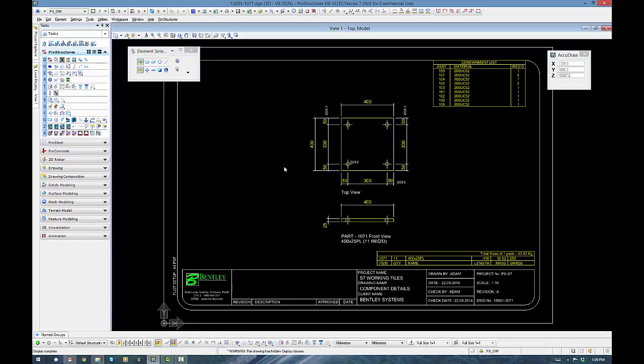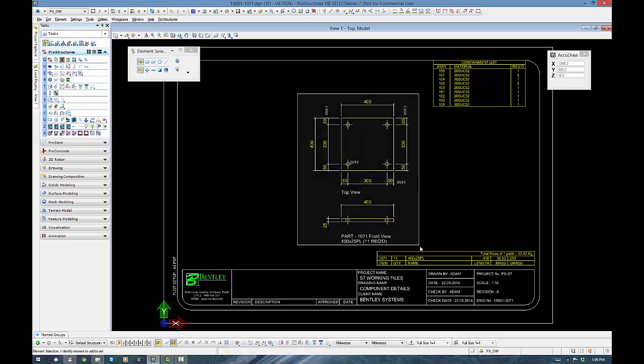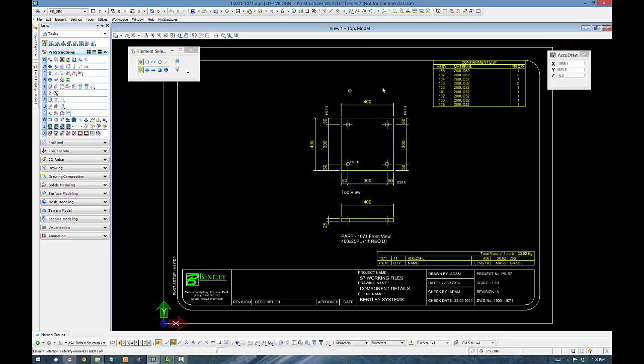Now this is really important. We open up the first one, and then from now on, we're going to go through another way to open them after this. But you can see that we've got our detail here. We have a containment list that tells us the groups that those parts get welded to. We have a material list here which should mimic exactly what's in the component label. As well as we have a title block that's been populated. Okay, so generally the single parts will try and fit on an A4 1:10 out of the box, unless it's too big from there.